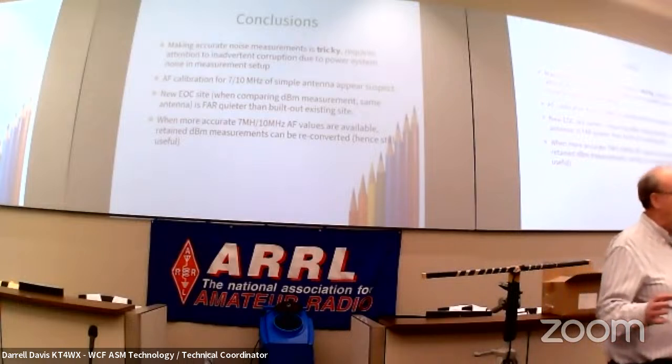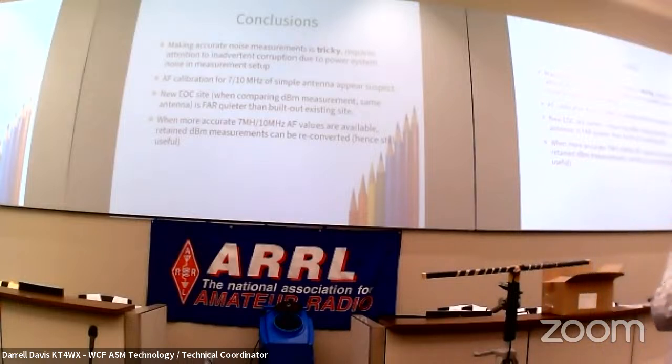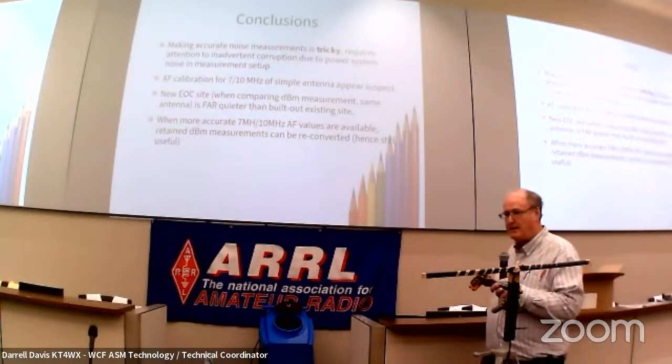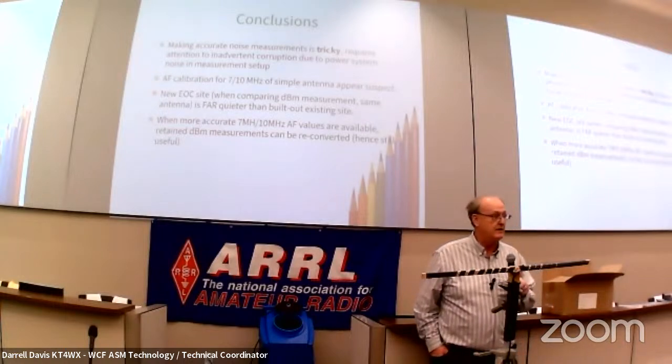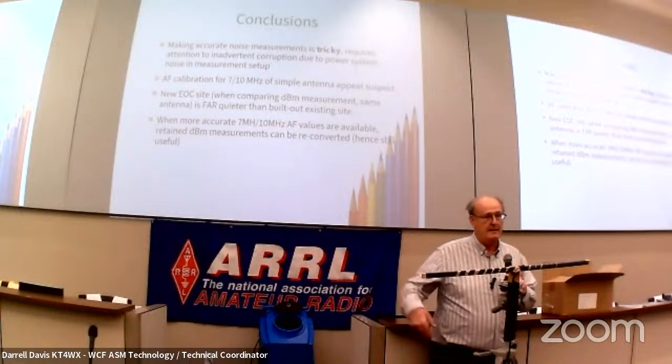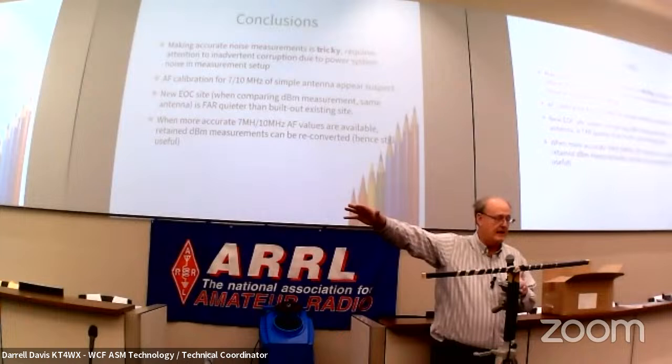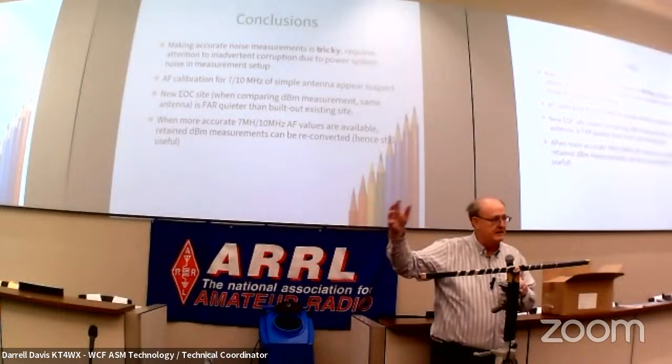So it turns out that there are ways to do that. If it's an industrial device, there are industrial filters. They're all over. The marketplace is littered with them because everybody has the same problem. And you can easily buy a big filter in a big box that you screw to the wall, and you get an electrician to connect it up. And it filters the power going into this big honking thing that you bought. And it will make the power wiring a lot quieter. And it's the power wiring in your building that is the antenna. That's what kills you. It's like a Faraday cage in reverse. You're living inside the antenna.